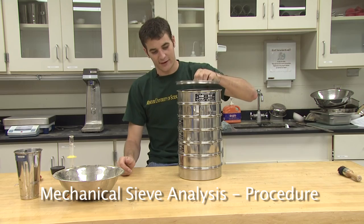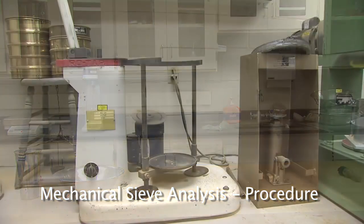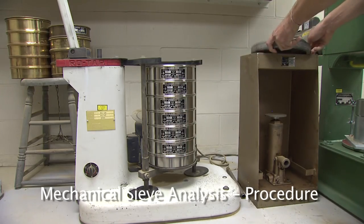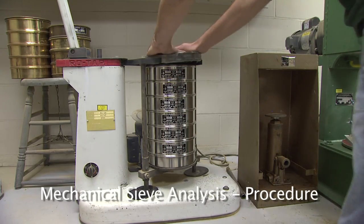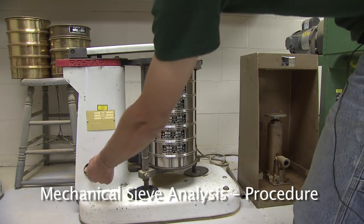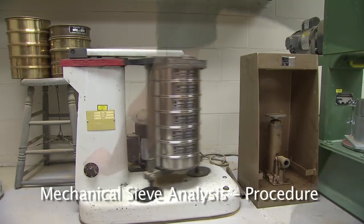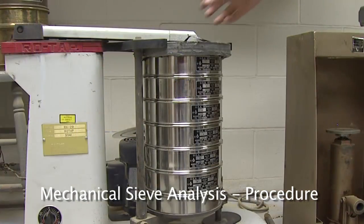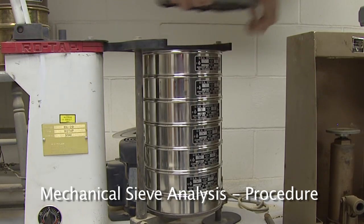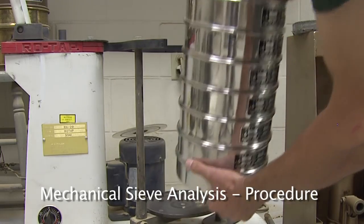Place the lid on top of the stack of sieves, and with 2 hands, carry the sieve stack into the shaker room. Load the stack of sieves into the mechanical sieve shaker. Place the shaker lid on top of the stack of sieves. Lower the shaker hammer and turn on for 10 minutes. Remove the shaker hammer, take off the shaker lid, and with 2 hands, remove the stack of sieves from the shaker and carry into the other room.